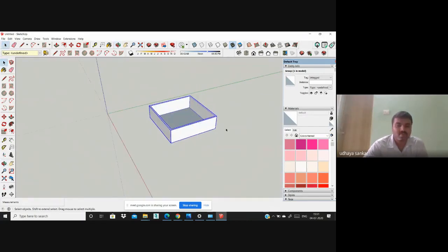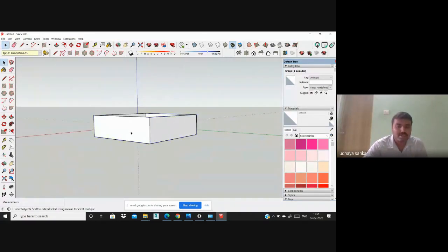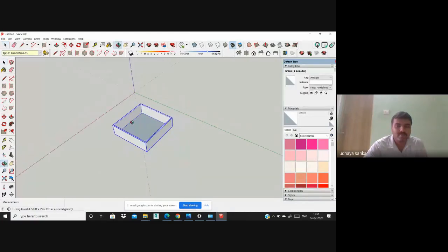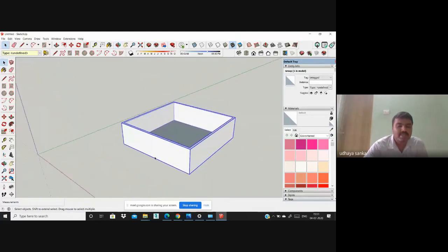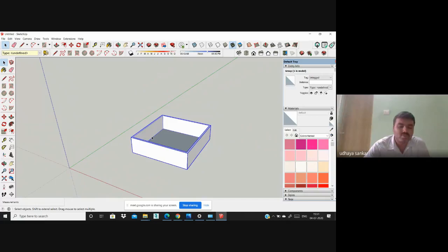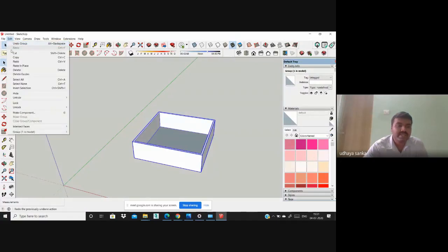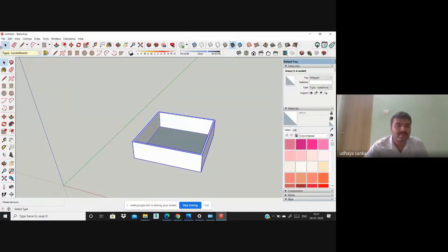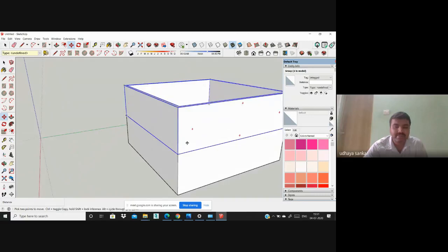All parts come from one, right? All sides, the bottom, the walls, all side walls, interior and exterior walls, come from one portion, that is the group, right? I simply created the group. Then I need G plus 2 or 3 floors, right? How to create them? You simply select this ground floor, go to edit, select copy, then go to edit, paste. Now you'll see it is automatically created, the G plus 1.